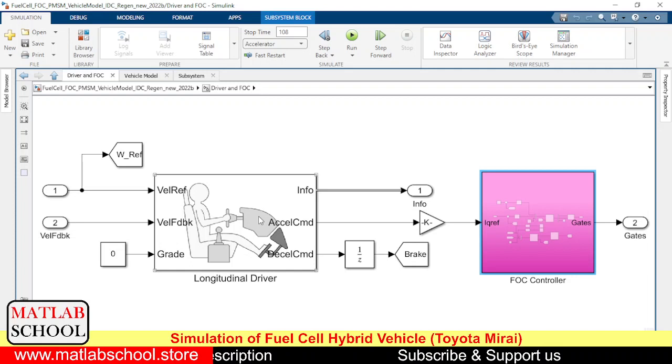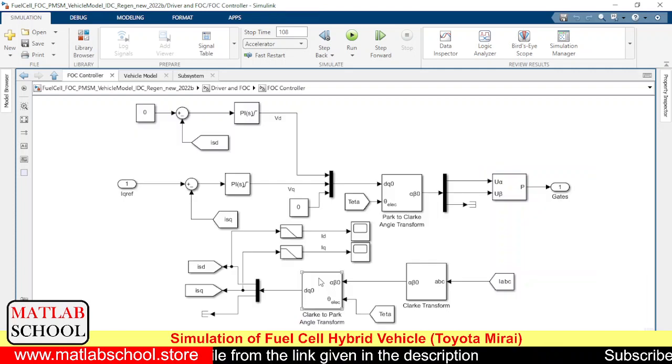As you know, in the case of BLDC motor control, we will be giving the IQ reference from the previous stage, and the ID reference will be 0. With this ID value and IQ reference value, we are comparing the actual values of ID and IQ. We get those from the IABC values after going through the Clarke and Park transformation. So we go for ABC to alpha beta transformation, then alpha beta will be converted to DQ.